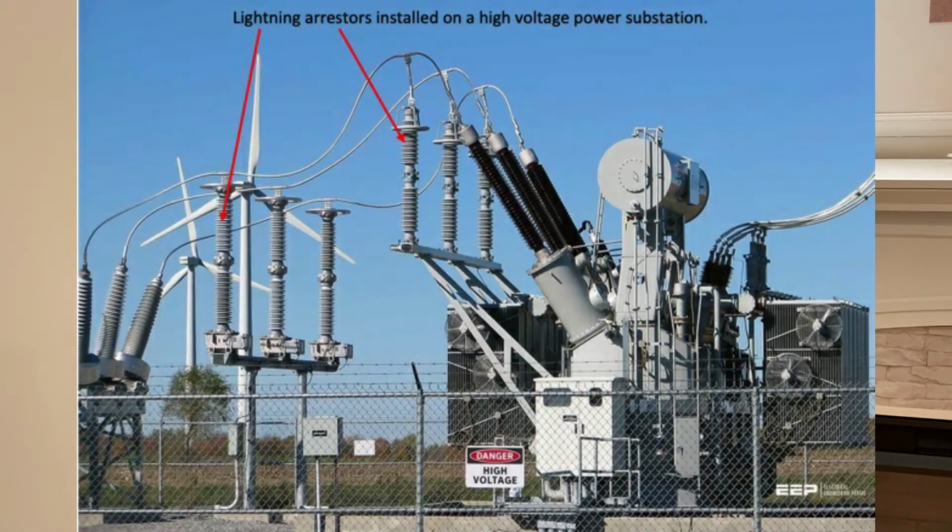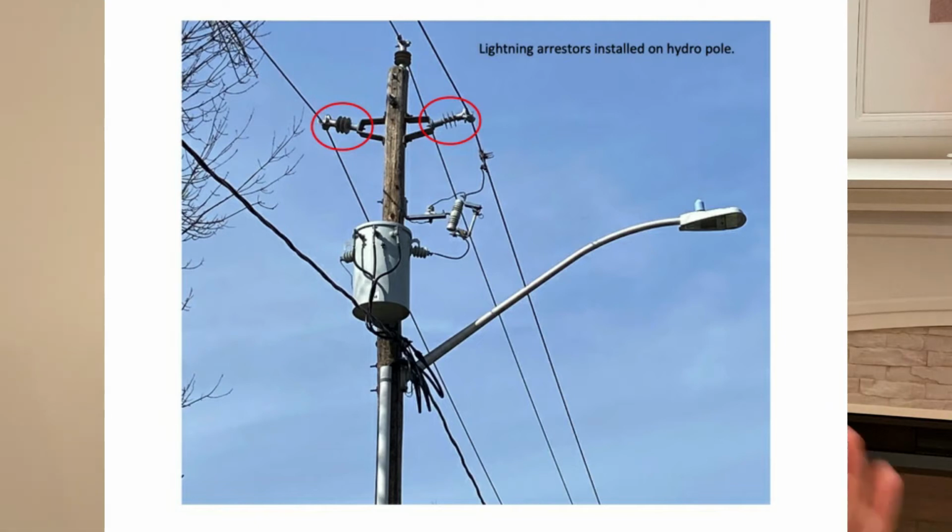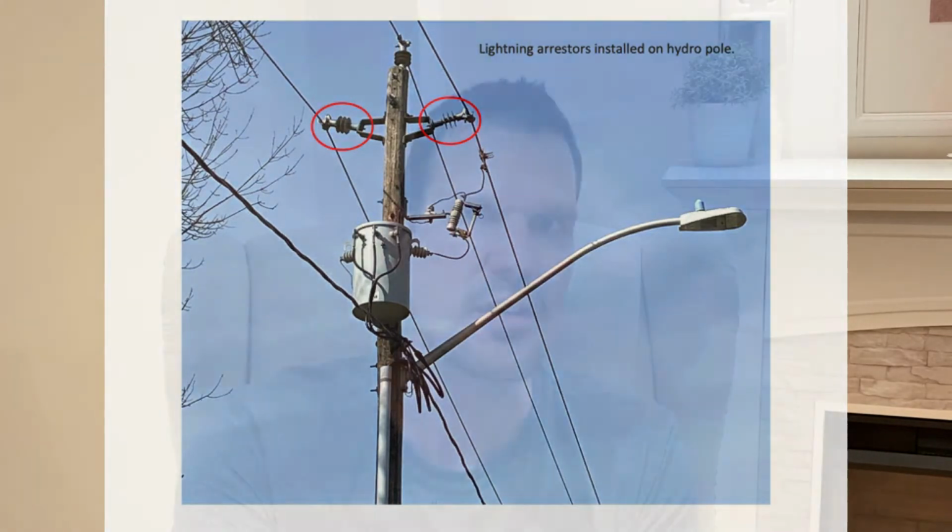And in the industrial automation sector where I came from, we used what are called lightning arresters. We used to put these on sensitive machines to protect them. If lightning does hit the building and there's potential to damage your equipment, the lightning arrestor will discharge a lot of that electricity directly down through the grounding electrode into the earth. So again, we have another scenario where the grounded electrode is conducting electric current.